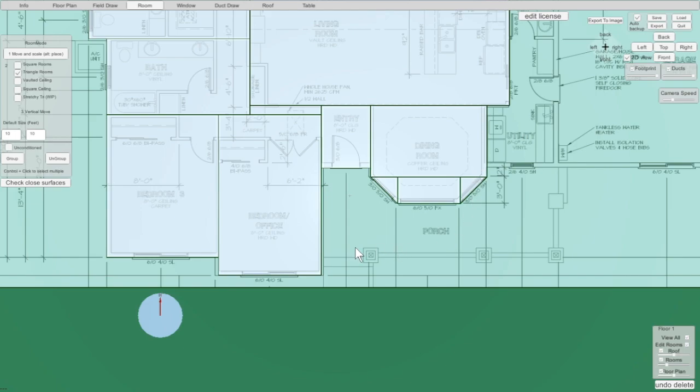So, and then you'll want to group these next. So you click on it, then you hit the Control, and then select all the rooms you want to group. Then come over here and hit the Group key. Now all those blocks are assembled into one room, and when you move it, they all move together. You can still size them independently, but they're all stuck together, and they will be saved in the tables for the takeoffs as the room. We'll name it the dining room, and all the areas from those blocks will be added together in the room.